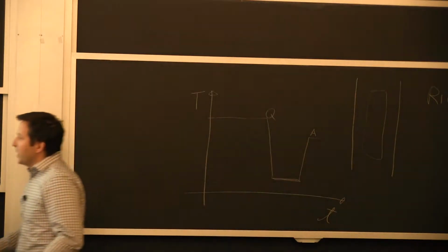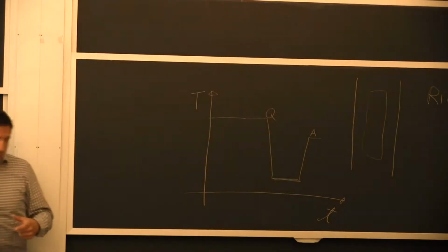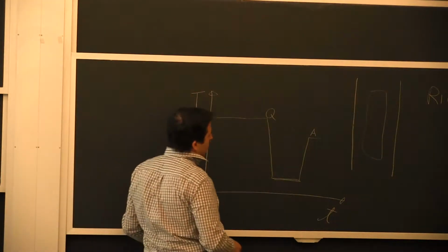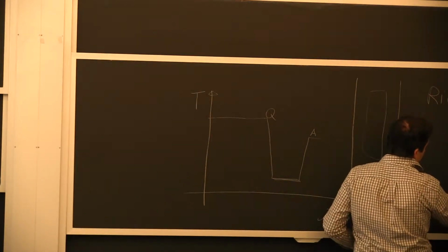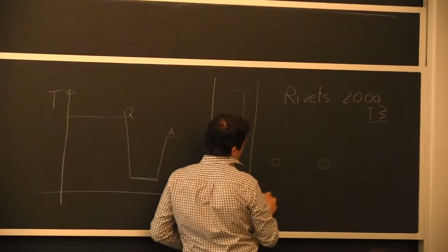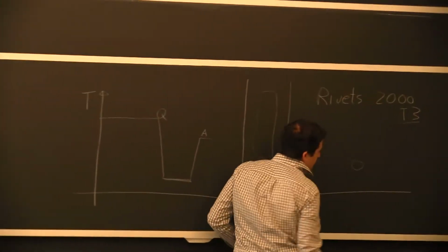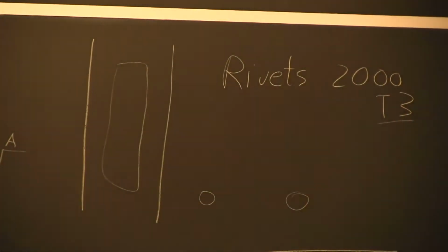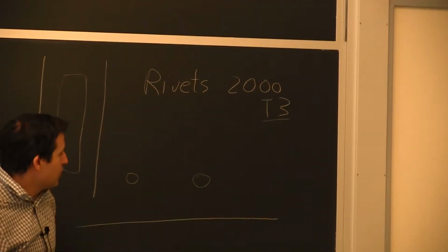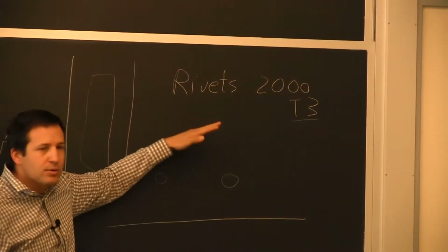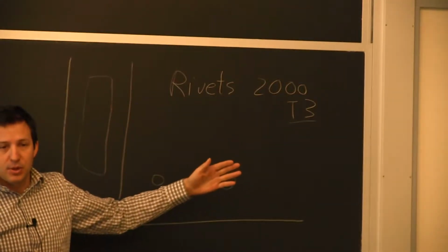Then you go through a phase where they are a little bigger. So if we think about this, this is in the aging process. If we have a particle, and say we have another particle here, the dislocations are always linear defects. So you have a line that's trying to come to these 2 precipitates. If it can cut through it, there's not much going on.